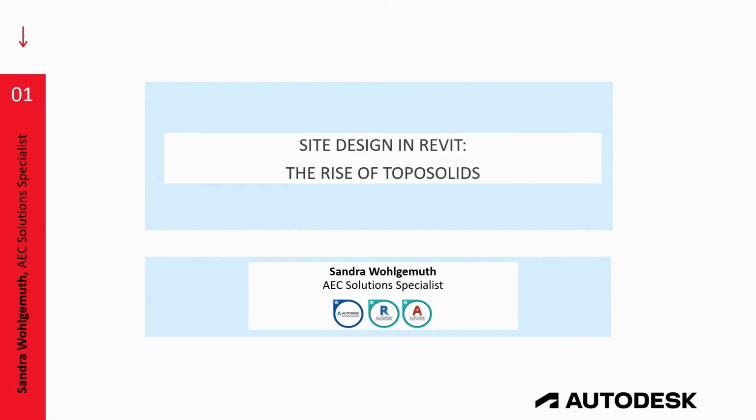My most important driving reason to do this webinar today is because the Toposolids tool is one of the tools that has changed immensely in the past 3 releases of Revit. They did the whole big revamp in 2024. So everything that was in the topo surfaces before and up until 2023 disappears completely in 2024.